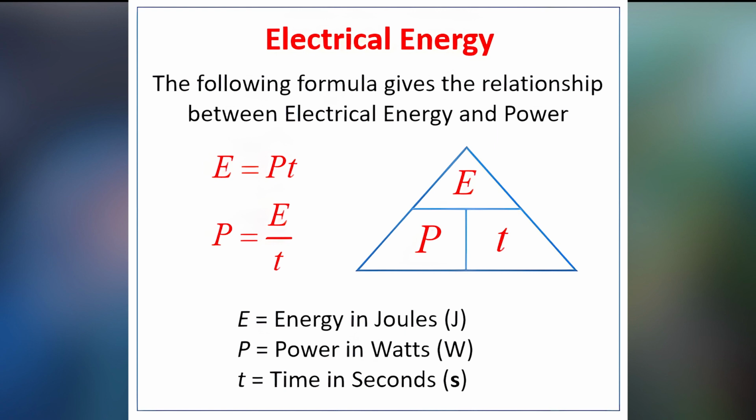But when you take a kilowatt and multiply it by hours, that then becomes an amount of energy because you've taken energy per time and multiplied it by some time unit. So a kilowatt hour is not a rate of energy use anymore. It's gone back to being an amount of energy. But that's kind of weird because what we've done is we've taken an amount of energy and then divided it by time and then multiplied it by time again. So saying kilowatt hours is kind of like saying joules per hour every hour. It's sort of weird to do it that way.